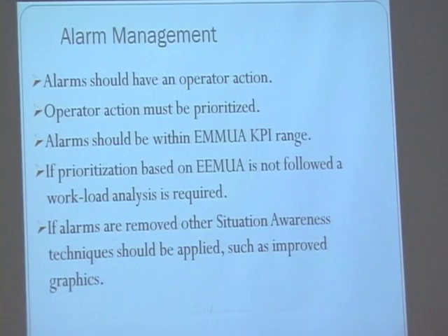We used to have a practice in the old days on panels, where the operator used to look down the panel, and everything was calibrated so that when it was good, it was always on a straight line in the middle, down all the trends. And you could stand there and look down the panel and see everything in a complete straight line. You said, everything's lined out today and it's good. And if something was out of shape, it would be out of line. And it was easy to spot.